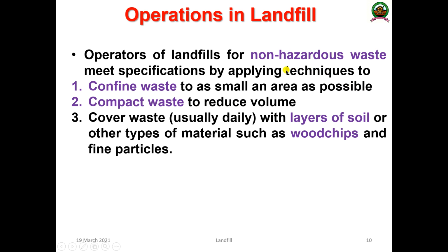So the operation of a landfill for non-hazardous waste material which meets specification uses techniques such as, first, confining the waste to as small an area as possible, so you need to utilize the space. First of all, nowadays we don't have space. This landfill requires a lot of space, so you have to confine the waste as much as possible, and then compact the waste to reduce the volume, rather than dumping and spreading it throughout an open ground.